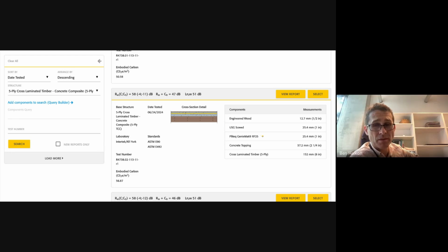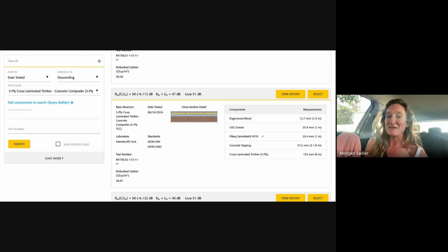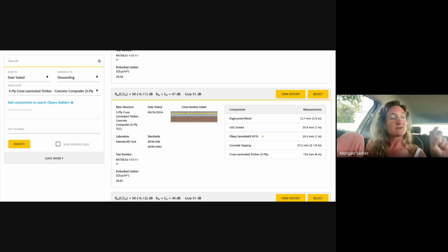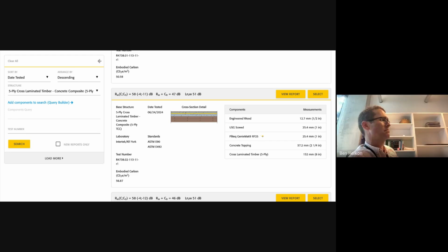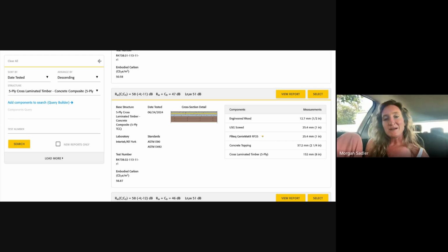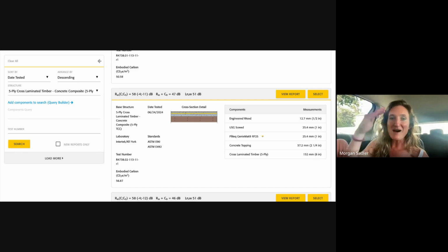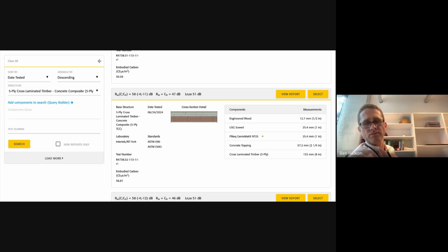1.2 meter, not 1.2 millimeter. Did you say 1.2 meters? 1200 millimeters, yes. So that it was infinitely stiff, so that we could really start understanding just the response of the material from a force pulse standpoint. To us that was a very objective, apples to apples way to understand the efficacy of products. It's because of that drop tower that we're able to do all this prediction modeling, and really understand contact time of the source. Makes sense. Anyway, I could ramble on about it, but maybe that's for another time. I just picked up on it because I wanted to mention that we have a drop tower.